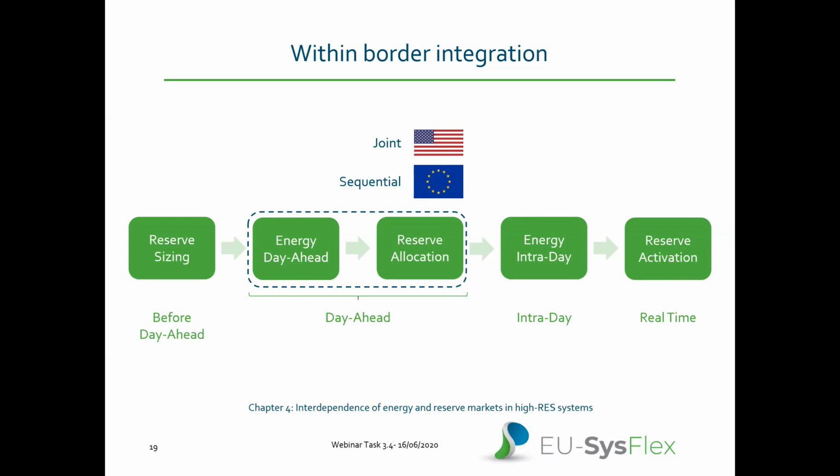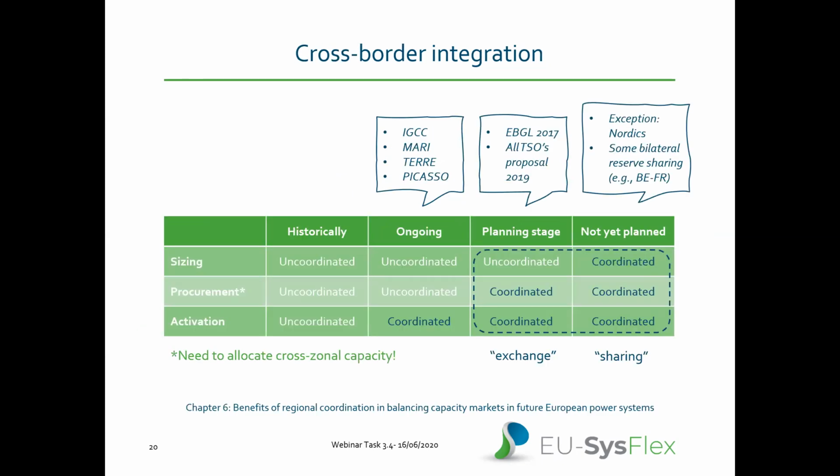Another element, a possible element of integration, as I said, is cross-border integration, where we really think about the reserve side of things. So there's the sizing, procurement, and activation, which historically have been uncoordinated. But now in recent times, there is already some coordination ongoing on the activation side with the projects that are listed here. And then there is also now some action to sort of plan action on coordination on procurement. And it's from this stage that things also get a little more complicated, because then we need to start to allocate cross-zonal capacity on the day-ahead stage at the latest, which then impacts the availability of this capacity for day-ahead and intraday energy markets. And then one step further than what we call here reserve exchange is reserve sharing, where